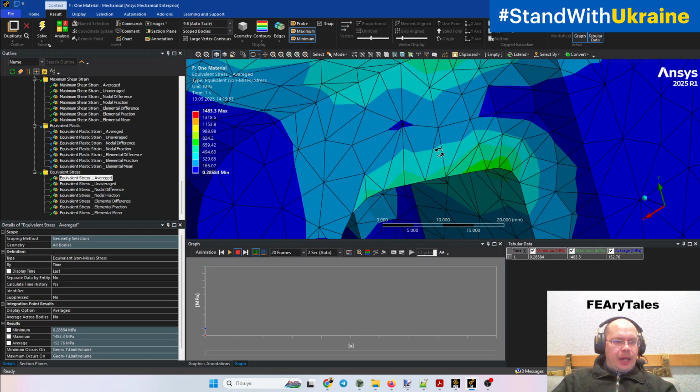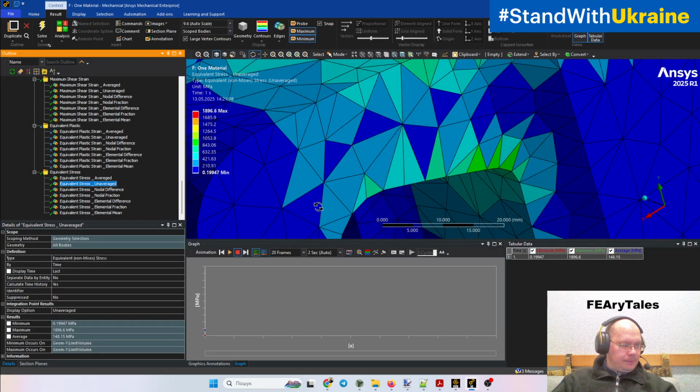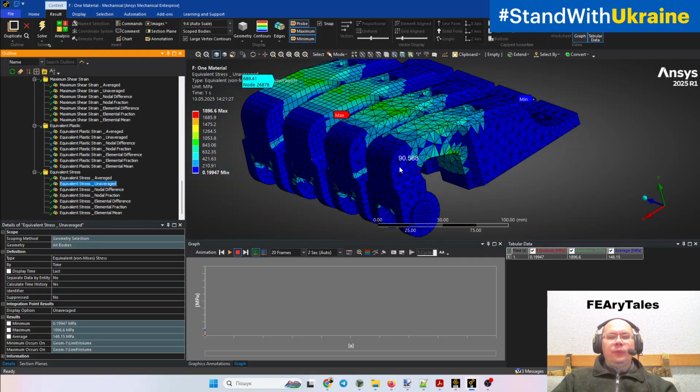But when we switch from average to unaveraged, the picture is very different. We can see here no smooth line, even with peaks, because every element is colored with its own color. And if we take a probe, we can see that no matter where we try to obtain the probe, we have the one result. If we switch to another element, the results change. But inside of the element, we have the same result, because linear tetra has the one stress and strain value through the element.